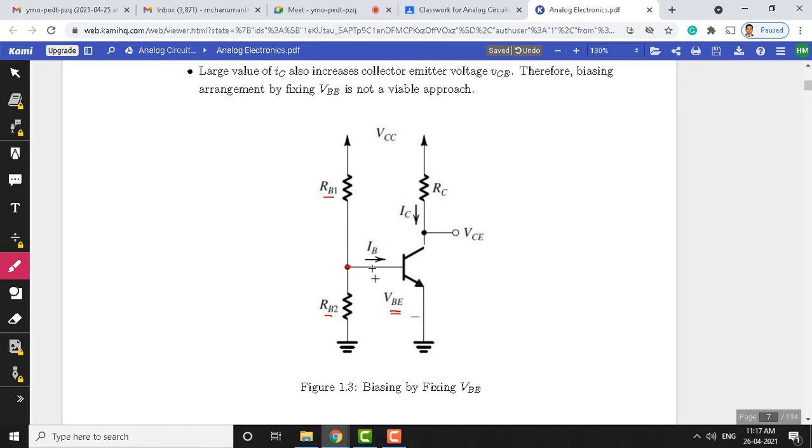This voltage is applied as an input for the BJT, and it is labeled as VBE, the base emitter voltage. Now you can see that the output voltage is VCE. These are all DC voltages here. We need to set up constant DC voltage across the transistor circuit, so that any signal applied here, a sine or cosine, gets amplified when the biasing conditions are established. With the help of biasing schemes, we are establishing constant voltages and constant currents. At any instant of time, the output current should not vary with the transistor parameters. That is the kind of concern we have to ensure.